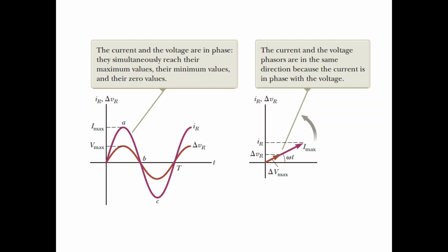So how we show it with a phasor is quite convenient for alternating current circuits. We introduce vectors with magnitudes which are equal to maximum values of the considered quantity, either current or voltage. Then we consider that this phasor vector is rotating counterclockwise with angular frequency omega, which is the frequency of the AC power supply.